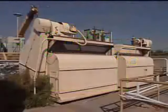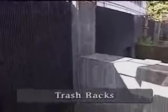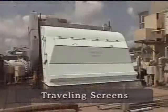There are usually two types of screens used to filter out trash in a once-through system: coarse screens and fine screens. The coarse screens, or trash racks, sometimes called trash rakes, are large mesh screens that filter out large debris such as logs or branches. The fine screens have a smaller mesh to filter out smaller debris. Typically, traveling screens are used for this purpose. They can be rotated in and out of the water as needed so that the debris can be cleaned off. The motor-driven traveling screens cycle based on the differential pressure across them.